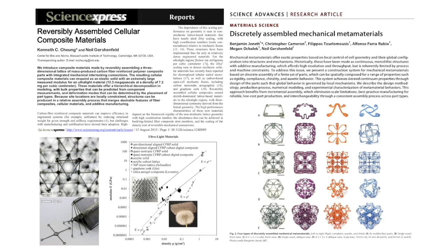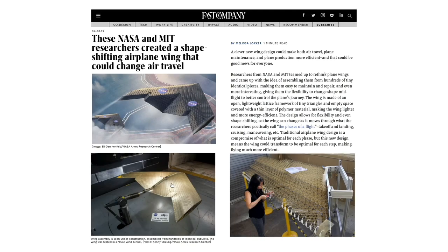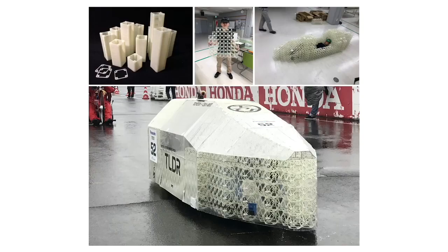Then here we showed, starting from the same base material, that's rigid, that's flexural, that's auxetic, that's chiral. We can design very anisotropic material properties just by composing those couple building blocks. We used this with NASA. This is Langley's biggest wind tunnel, to realize a long-standing goal of purely morphing aerostructures, not by building a mechanism into it, but by effectively turning it into a mechanism. This was a high-efficiency race car with Toyota, where instead of a year of tooling, it was done with a direct write assembly process.